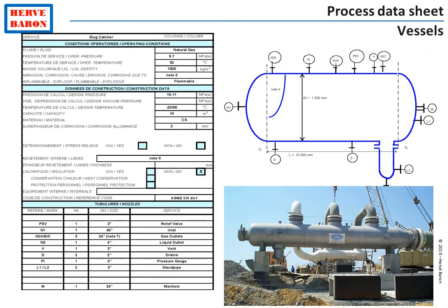Once the sizing is done, a process datasheet is issued by process, which shows the vessel dimensions. In addition, it shows the vessel operating as well as design conditions. Design conditions are conditions slightly above maximum operating conditions in order to allow some margin in operation.